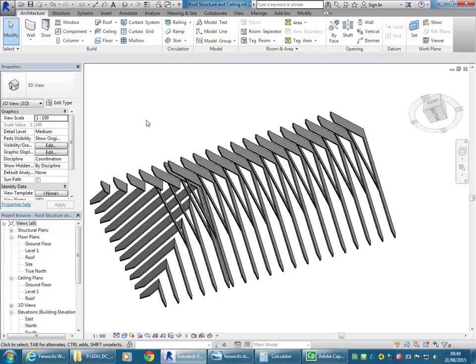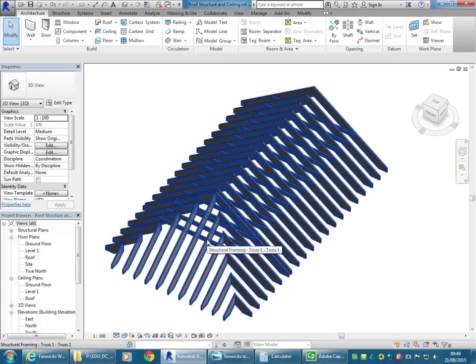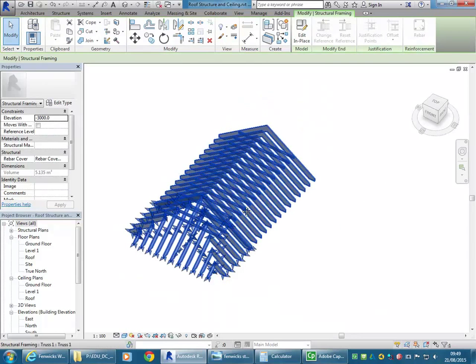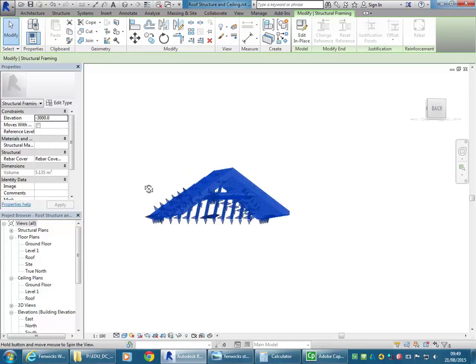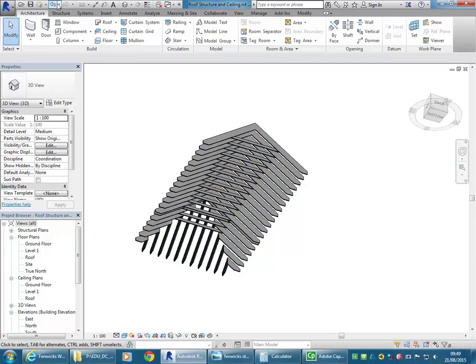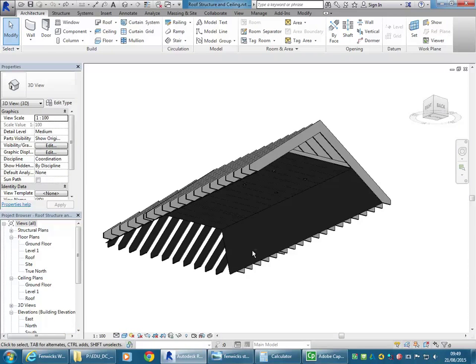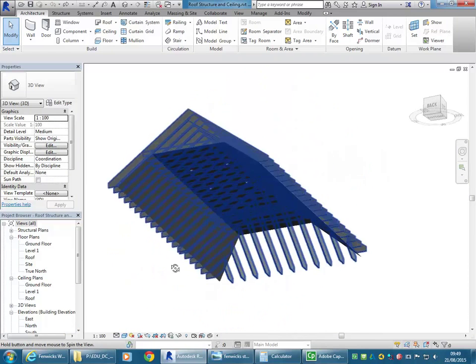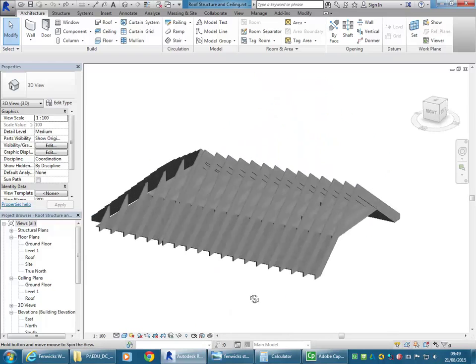Yeah, that's right. Click on it and delete. And if you only wanted the middle raft, just delete the, well, just, yeah, sure. So just orbit so that you can hold down shift and press the middle mouse button, and that's a better way of orbiting than using the cube.